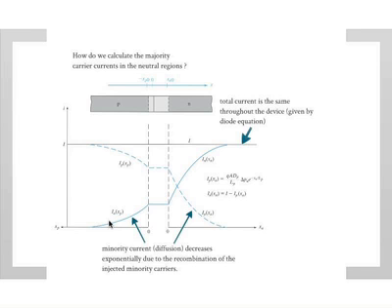Remember that the diffusion current, which is the minority carrier current, matters here because the majority carrier diffusion current is very small, since there's very small change in the concentration gradient of the majority carrier. The diffusion current is proportional to the rate of change of the minority carrier, in this case the electrons in the p-type.